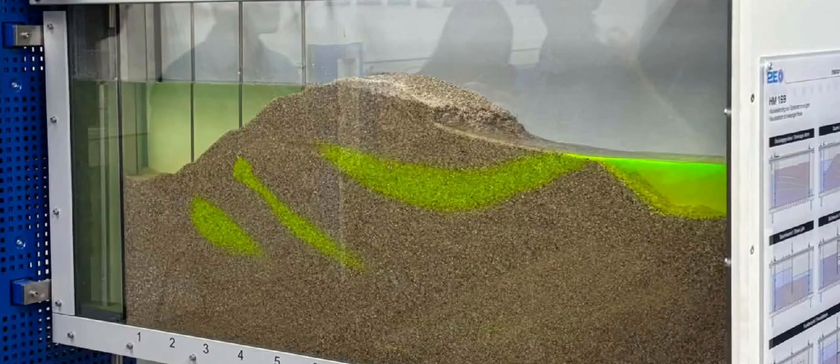In geotechnical engineering, analyzing an earth dam model inside a hydraulic drainage and seepage tank allows you to visualize how water moves through an embankment. This experiment lets you plot the phreatic line, the top water level line, and map out a flow net, a grid of flow lines and equipotential lines to calculate seepage discharge and assess piping risks.